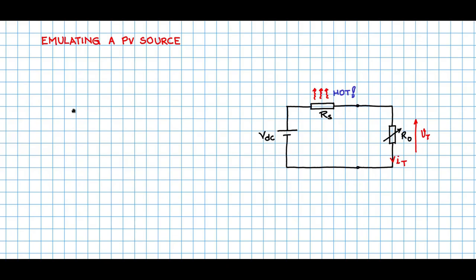Let us shift this circuit this side. Now this is what I want to replace, so I will remove that, and instead of that VDC source we will be having some electronic circuit here which will link up there. We would like to draw power from the 230 volts grid, the AC mains. So let us draw a transformer. It is not a transformer, it is an auto transformer. So we would like to have an auto transformer there so that you can draw variable voltage from the grid.